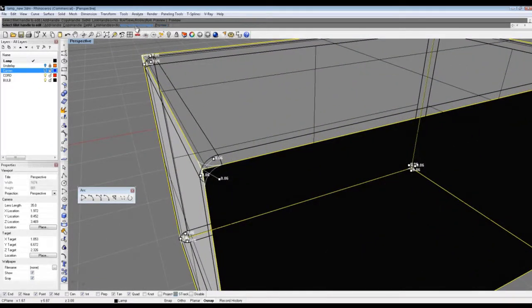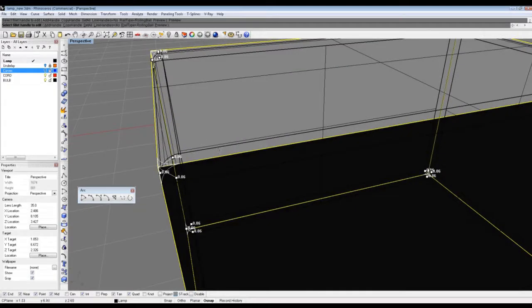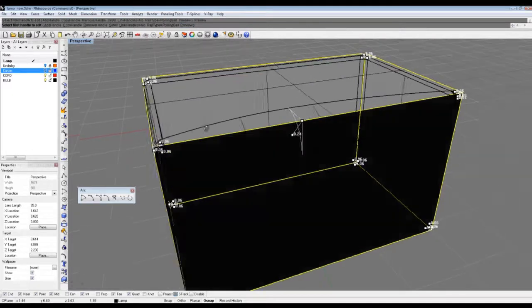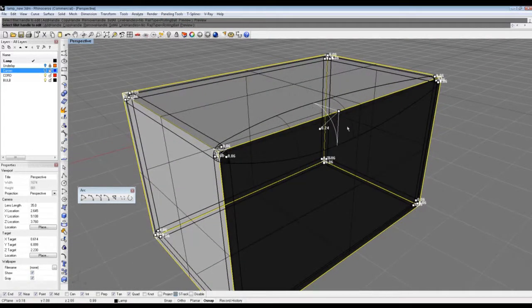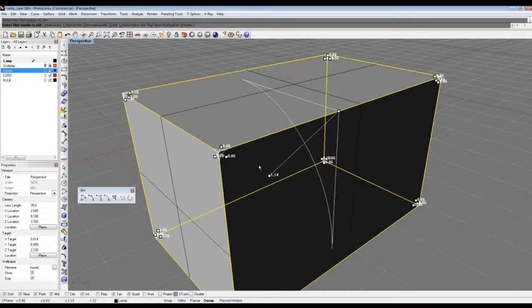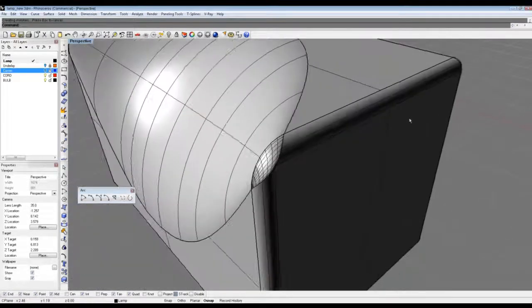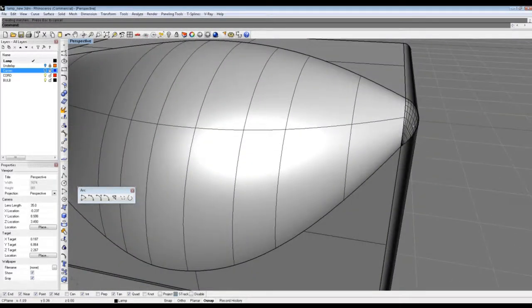Now there are all sorts of different sections in here that you can mess with. One I often use is to add a handle and then edit that handle and make it bigger or smaller to see how that affects my fillet. If I click on preview again now, I'm going to see that fillet there is not in conflict with anything. So I might get it to that point and see if that messes it up. And sure enough, it was able to make that big fillet, but not before messing up these corners.